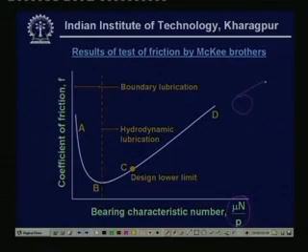This is the thing. Now, if this is a bearing and it is acted upon by some load capital P, and this is the diameter of the bearing, then that pressure is the total P divided by the projected area, that means D into L. Okay. So, this projected area gives you the pressure of the bearing. So, considering this particular fact, we come down to what we understand by this particular plot.